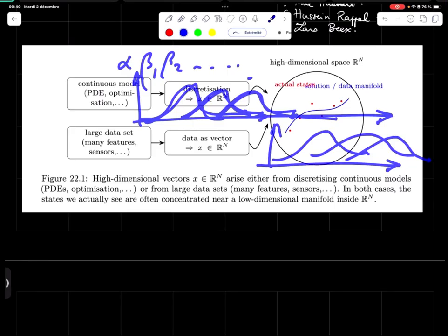And so when you do the building code, you need to take into account the combination of all these particular loads, and you need to take into account the worst possible case, because you want the ultimate load that the structure will undertake. So you are going to look at the same time, having the maximum snow load, the maximum wind load, and the maximum earthquake load all coming at the same time, which is very unlikely, never happens, but you're going to design your building against this, such that you're sure, more or less, that at least these combinations of events are not going to ruin your building.